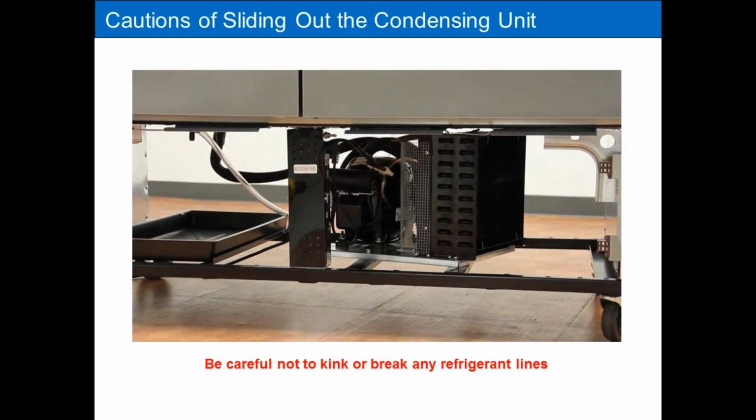Now, I did come to realize that it wasn't how I pushed it in that caused the problem. The suction line had a rub-out already started, and I just aggravated the situation by pushing it back in. Luck of the draw is that I pushed it back in and it gave free. In any case, be cautious anytime you're pushing the condensing unit back in or taking it out of its cavity. You may create other problems that you were not there originally for.